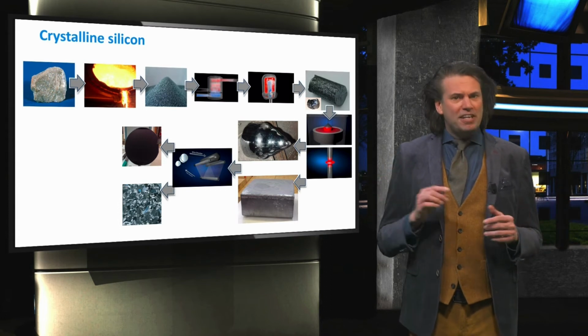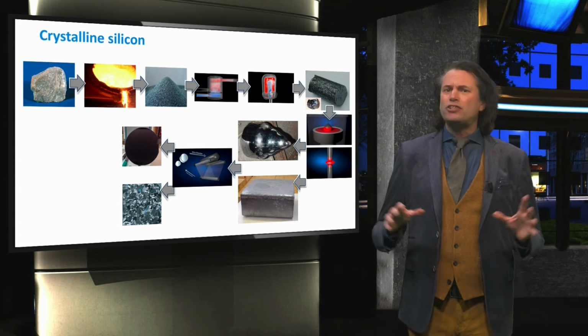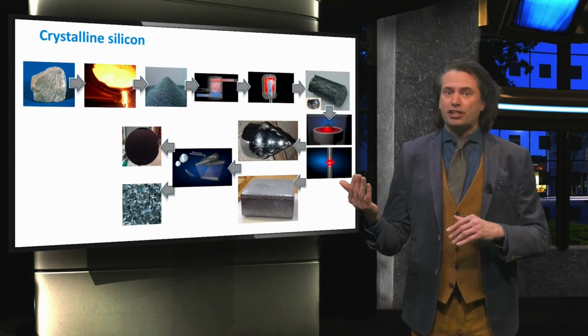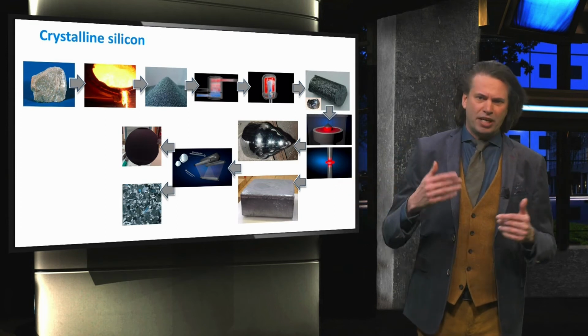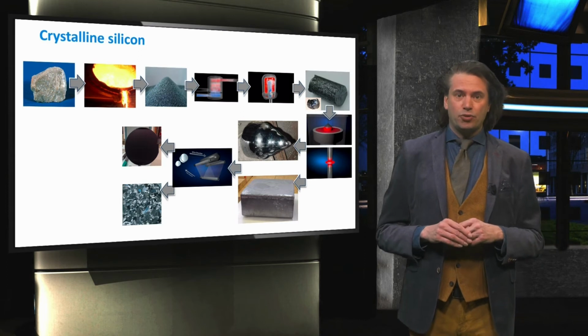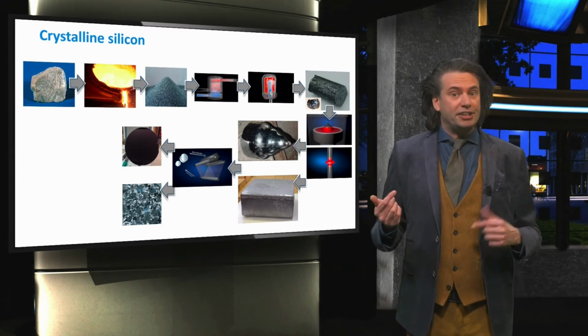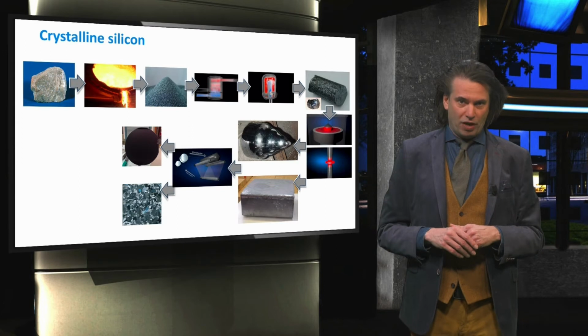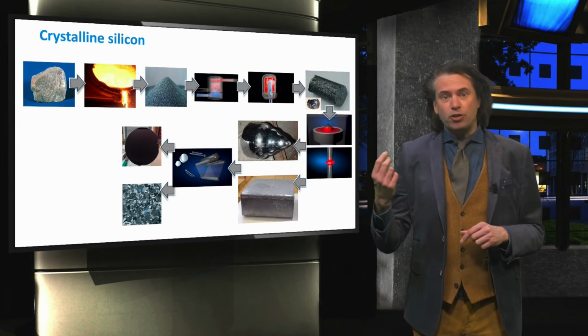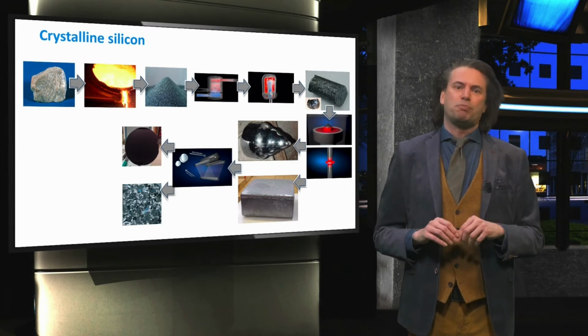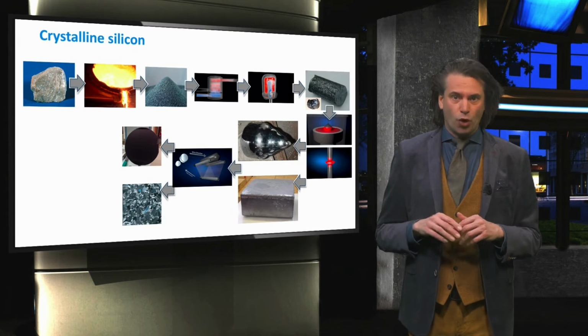For a PV device to work, however, we need to separate generated charge carriers and transport them. To that end, dopants are added to the crystalline silicon to create the N or P doped wafers. On top of these doped wafers, an emitter layer is processed with an opposite dopant type.